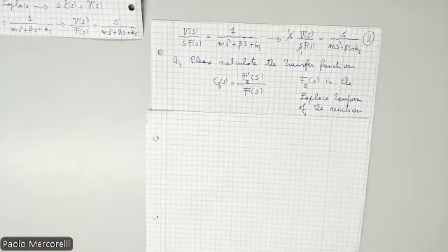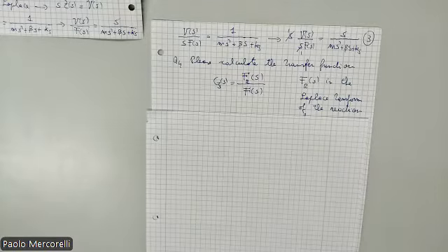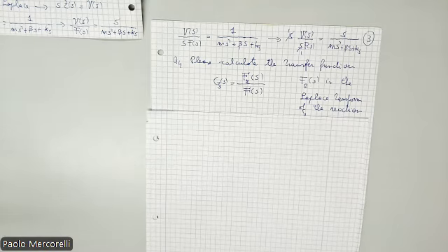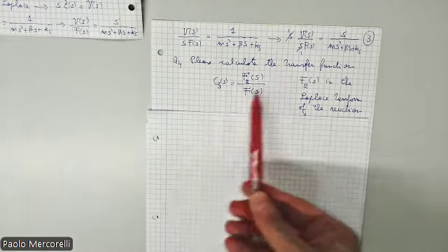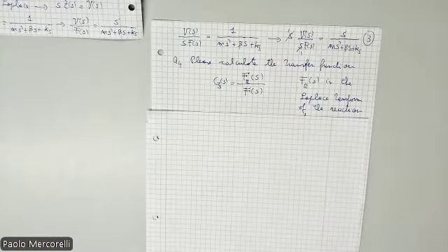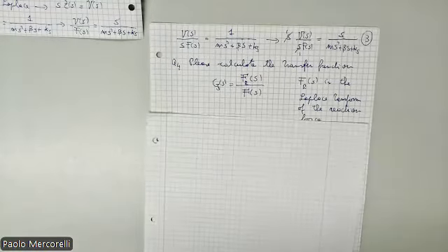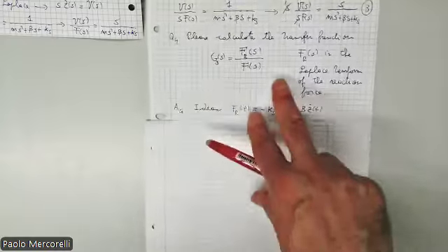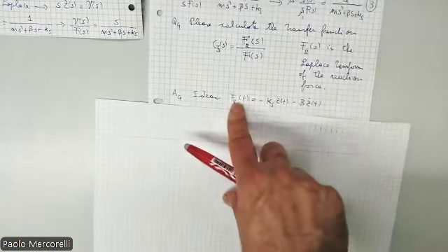Now, it's not extremely, but in the production system, very often it is important to calculate the reaction force. If I want to squeeze, or let me say fix, this object, the very important thing is don't destroy the object, to maintain it fixed without destroying it. This means very often we are interested in calculating the reaction force. F_R(s) is the Laplace transform of the reaction force, which we can define in this form.